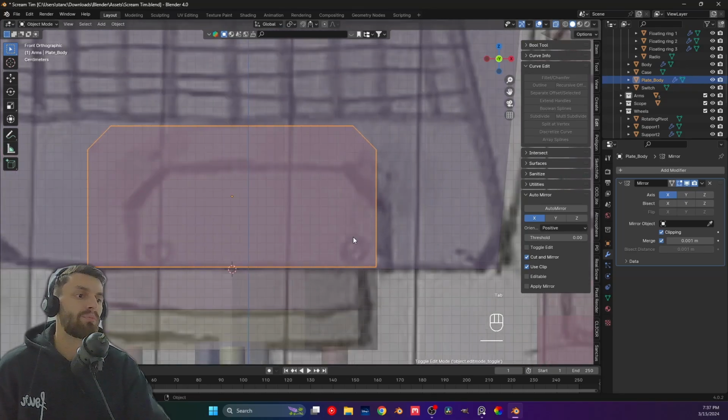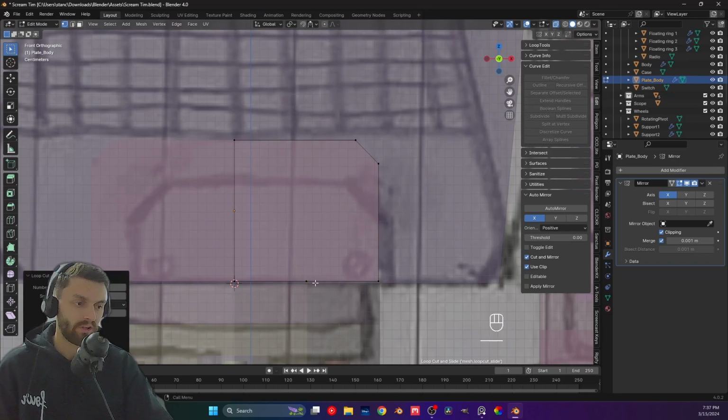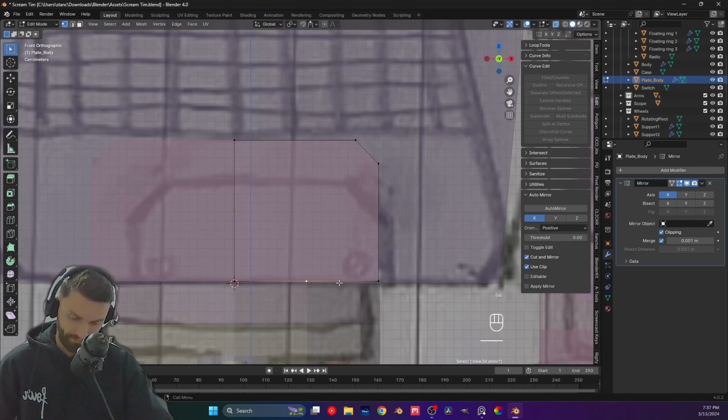And now press OK. Now there will be a small problem with the split, and probably some of you did already figure that out. Let me try to make a loop cut, and we can't. Because we have an n-gon, right? We don't have 4 vertices anymore. We have 5 vertices. So 3 here, 2 here. And to be able to actually make quads again, what we need to do is actually put this vertex right here.